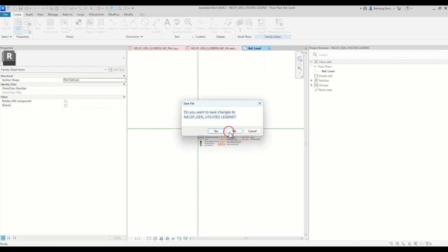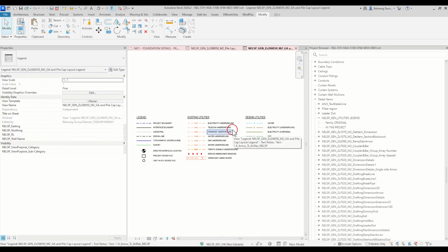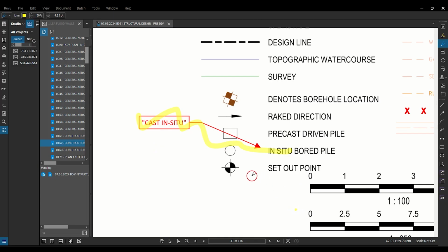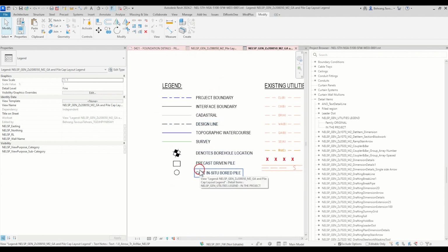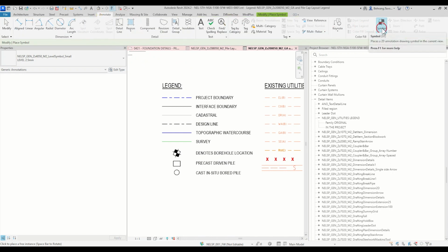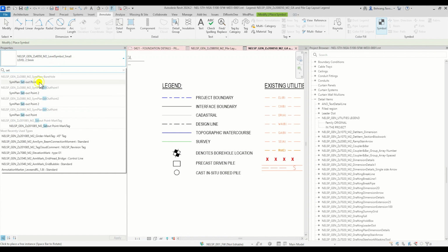So now, okay, now the challenge is we have to bring back that setup point. It's not a difficult task, so we know that this looks like that. I will just need to find this symbol. Let's go back here to the legends. Let's type SY for symbol. That only works for me. You have to go to annotate and just find this symbol. So I said SY for symbol. So let's say set plan setup points.